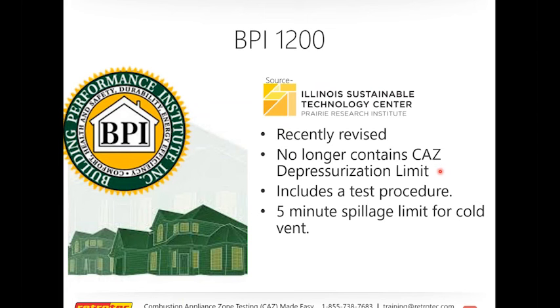Yes, the BPI 1200 standard does include a test procedure. And again, there is a 5-minute spillage limit for a cold vent. And there's a 2-minute spillage limit for a warm vent. I think that is a major difference between the BPI standard and any other standards that I'm familiar with.